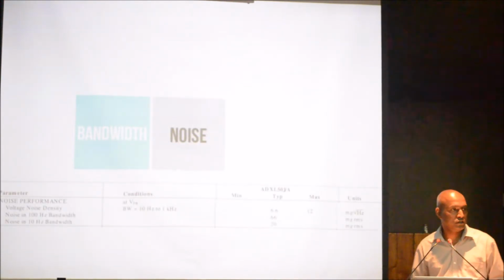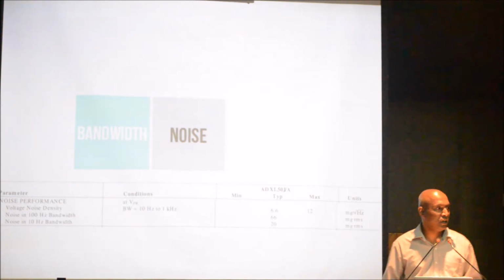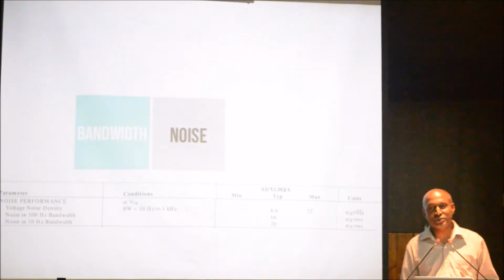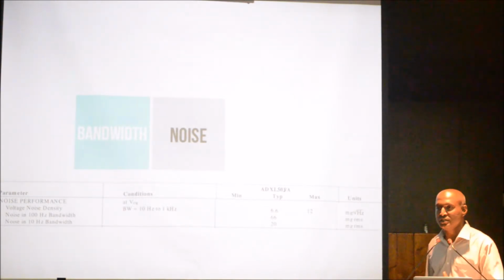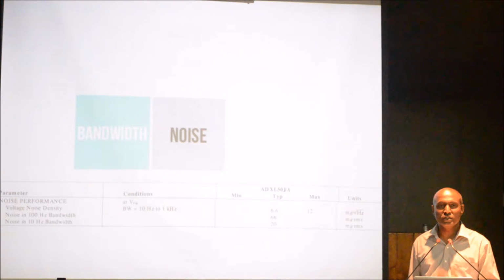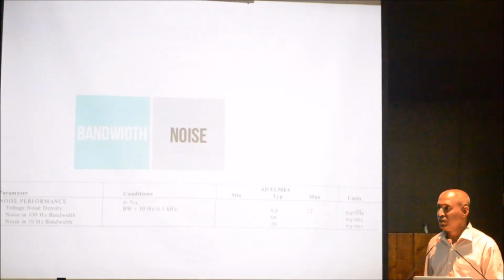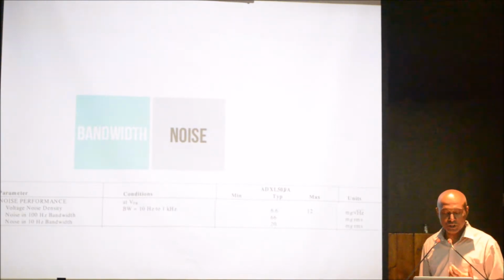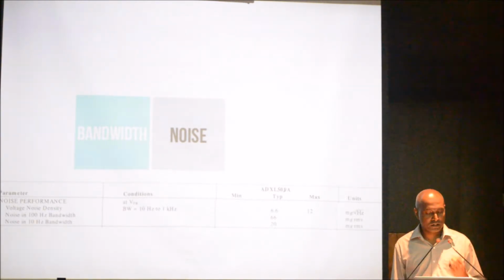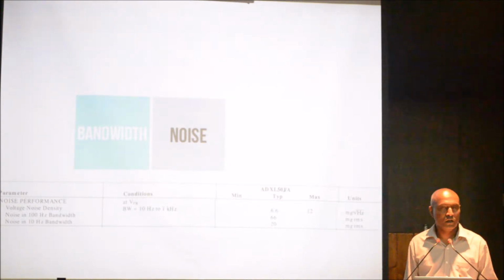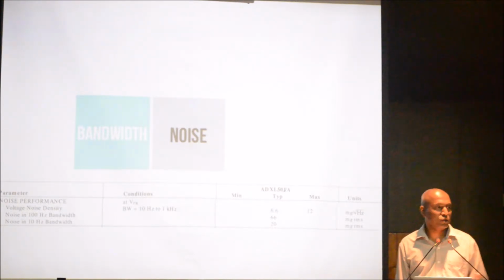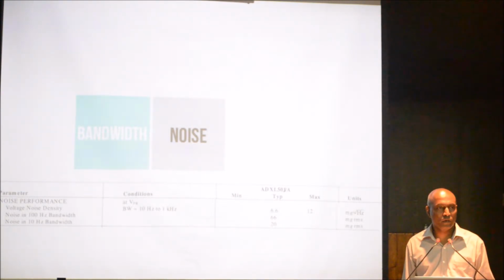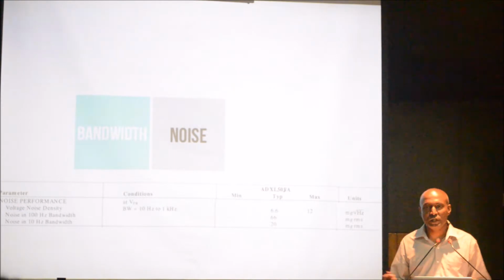Most importantly, noise. Now, when you read a value from a sensor, as I said before, the question we had was whether those values are valid, right? If it includes noise, and if we take noise as a valid output from the sensor, we are nowhere, right? So we need to know this factor very well. What's the noise ratio that we are talking about here? Mostly it is relevant to the frequency of the measurements. Then you can calculate the noise level that you would expect from the range that you are looking for.